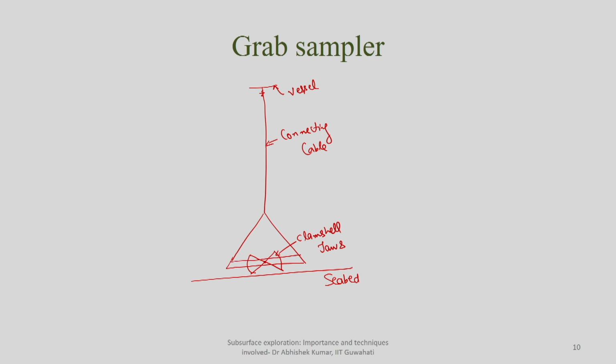but as soon as it reaches the surface, these jaws will be released. So the sampler will remain like this, but your clamshells will come in contact with each other and it will close from the bottom. So this movement will be happening from this particular depth.